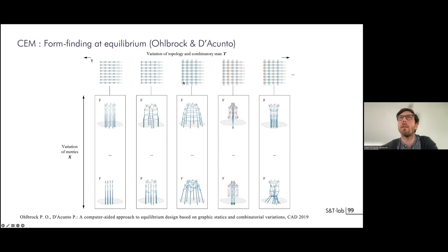Then you add rings at all the stages, compression ring that you can see here. You can start modifying the forces in the deviation, and it could be really something else. As you can see, these two topologies, we just shifted some elements from tension to compression, modified the values, and you have more structure with compression core and hanging structure.